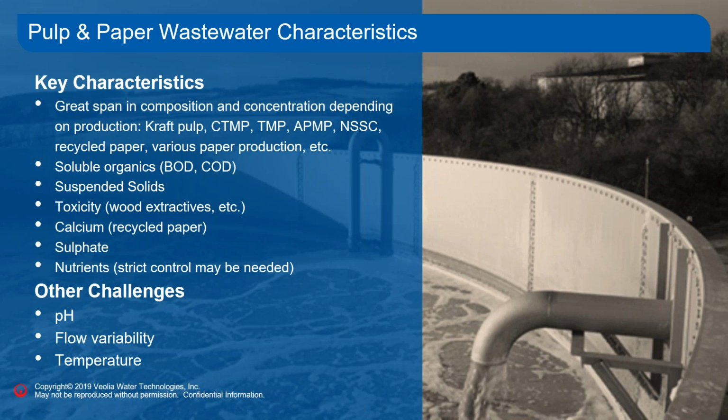Some important issues, especially for pulping wastewater, are things like toxicity. When you have different types of chemical pulping, residual COD or refractory COD can arise in the wastewater, and some of it can be toxic. So it is very important to understand all of that before you actually design your biological wastewater treatment plant.